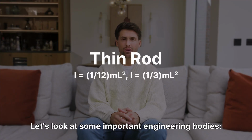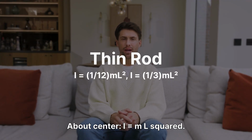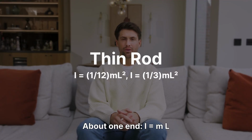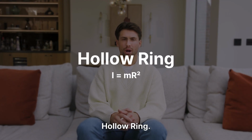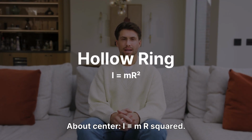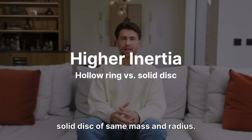Let's look at some important engineering bodies. 1. Thin rod. About center, I equals ml²/12. About one end, I equals ml²/3. 2. Solid disk. About center, I equals mr²/2. 3. Hollow ring. About center, I equals mr². Notice, hollow ring has higher inertia than solid disk of same mass and radius.